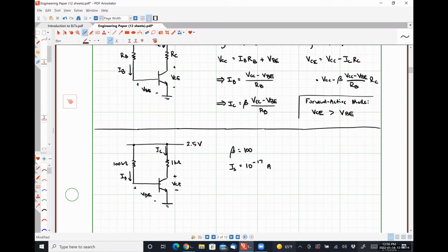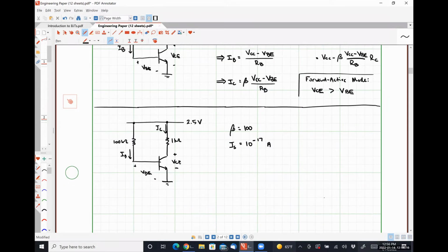So what we're going to have to utilize for this particular circuit is an iterative procedure, much like what we developed for dealing with diodes. Okay, so we're going to have to take a reasonably educated guess as to what our base emitter voltage is, calculate the collector current, and then see if that collector current corresponds to that base emitter voltage.